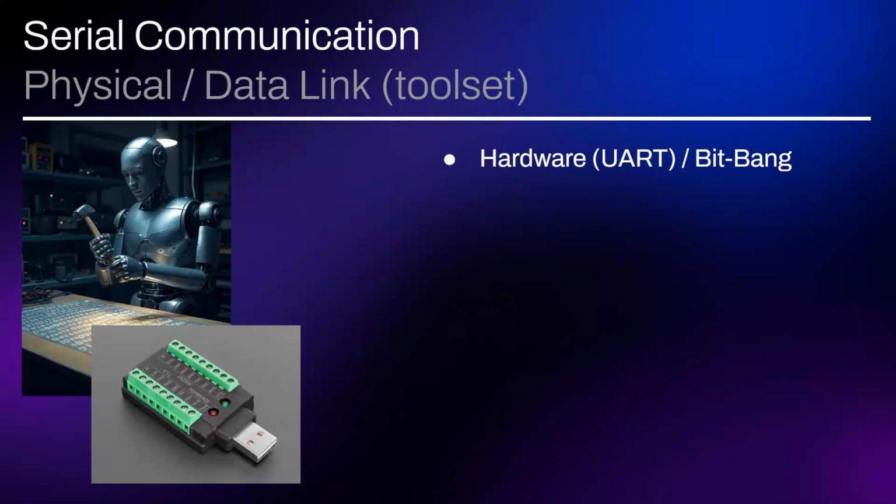So you read in the bits, and then maybe it'll send an interrupt, or maybe you're polling it for a bit to go high that says, okay, I've got some data for you. And you grab that 8-bit byte chunk out of there. So it does a lot of the work for you.